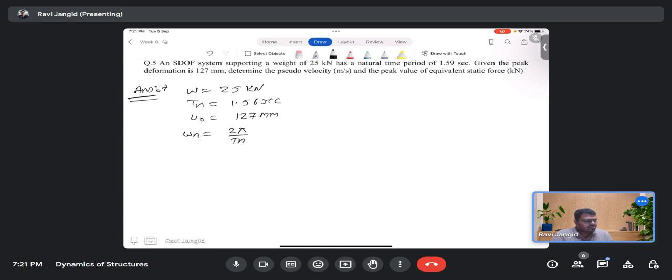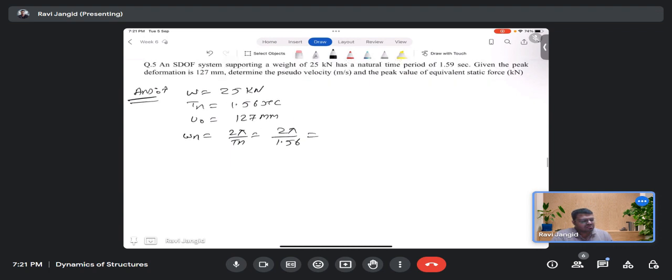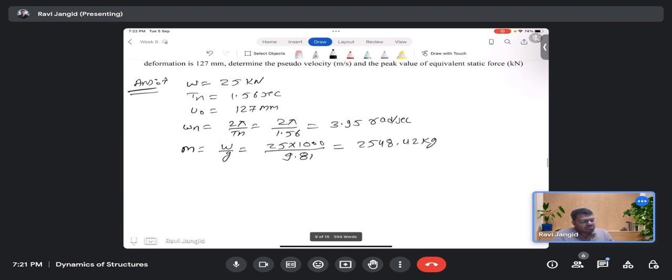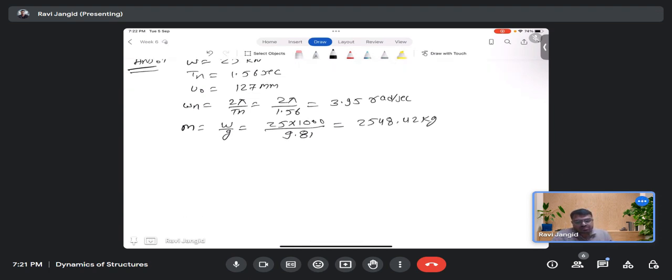So what is my omega n? Anyone? 3.951. So that is coming 3.95 radian per second. And what is my mass? That would be W by g, 25 into 1000 divided by 9.81. So that will be coming out to be 2548.42 kilogram. So can you give me the stiffness of the system?